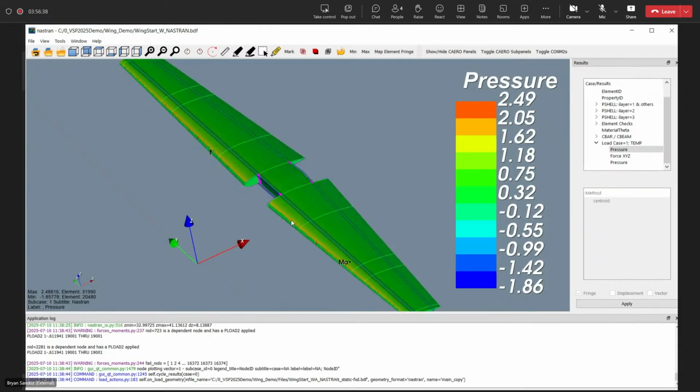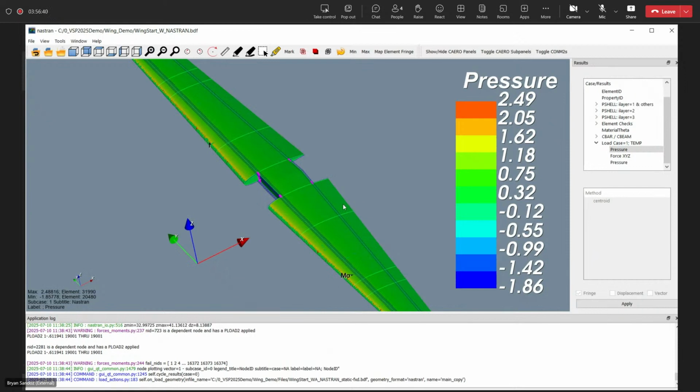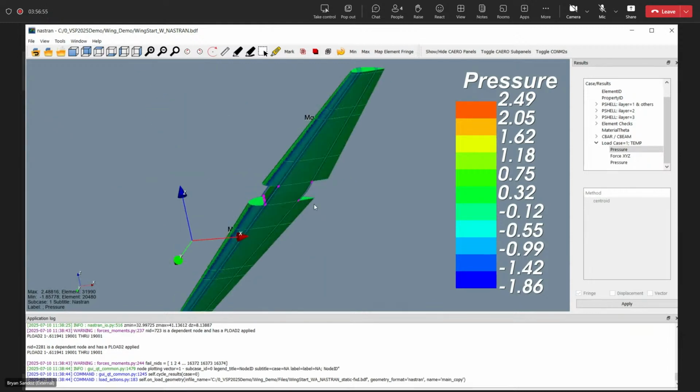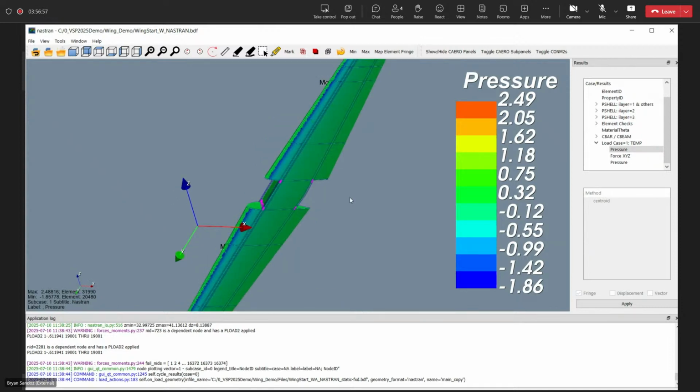The other thing is the distribution will look a little different, because it's taking that flat plate VLM, or that camber surface VLM, and applying half of it to the top and half of it to the bottom. It tends to focus more of the pressures on the leading edge than if you run a panel code. That'll look a little more sort of normal. But the key thing here is you have a pressure distribution.